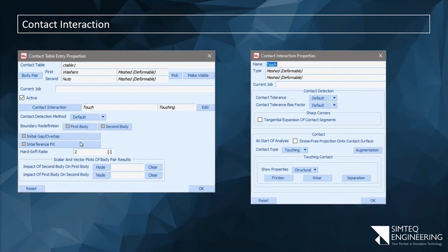Okay, so the two are not exactly the same, but they share a lot of commonality. We'll discuss the difference between them at a later stage then. And then there's a setting that says, well, if I have, for example, two meshes making contact, one fine and one coarse, by default, or the ideal situation, the fine mesh makes contact to the coarse mesh. We'll discuss why a bit later on, so don't worry too much about it.